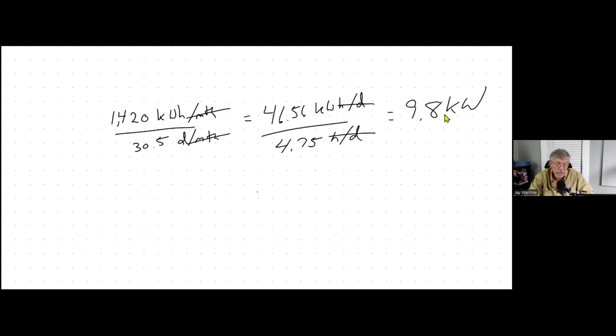But we know that our system isn't 100% efficient. We just figured it out. It's 5.5% inefficient in addition to whatever the inverter's inefficiency is. So let's say we looked at the inverter and the inverter is 2% inefficient. So it's 98% efficient. So that would be 7.5% inefficient, or 92.5%, or if we decimalize it, it's 0.925 efficiency. So this is the derate.